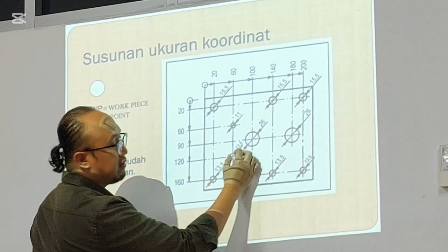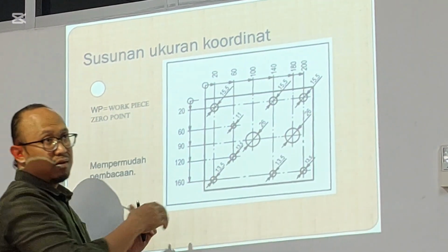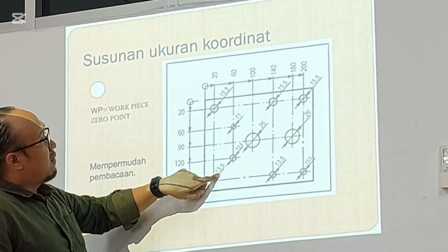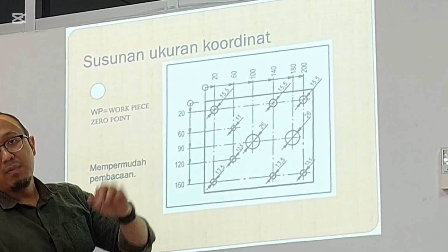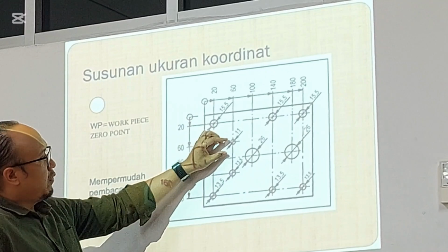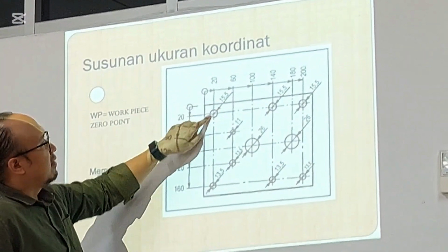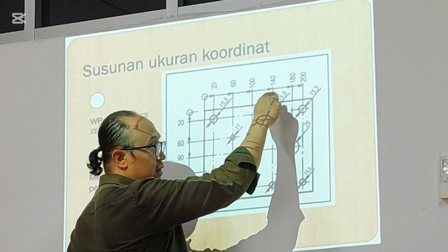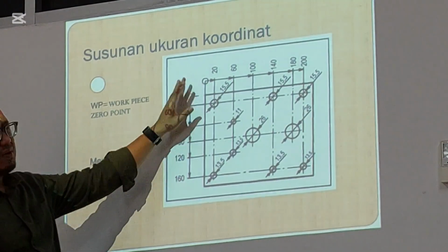Yeah, we can use this simply by looking at the size, because this hole and this hole are easy to separate. This one is smaller, but this one is big. But 13.5 and 11, maybe if you do not put some information, this one and this one may look almost similar. But if the difference is easy to distinguish, you can just put how many holes. See, for example, like this. These are 3 similar holes. So you can choose only one hole, maybe in this area. 3, dash, diameter 15.5. You can also use that kind.